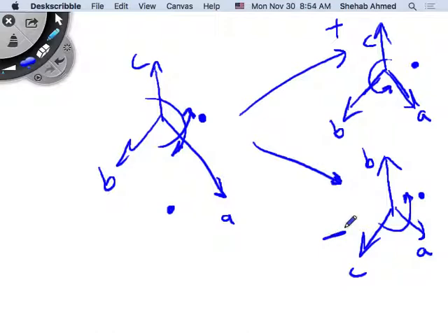What did Dr. Haytham say in the 338 course about flipping? Do you agree with this? This is what the symmetrical components theory says, right? It says that I can take this, chop it into a source that looks like this, and then do what? Take this and apply it to my three-phase equivalent circuit. This is balanced, right? If I apply it to my three-phase equivalent circuit, what can I do? Solve it using a single-phase equivalent circuit. Nice and simple, right? Same thing, I can take this, apply it to the same circuit. Nice balanced three-phase, use single-phase equivalent circuit.